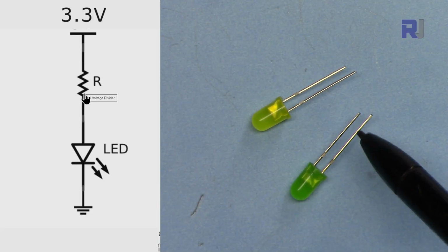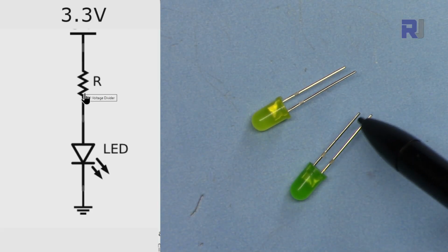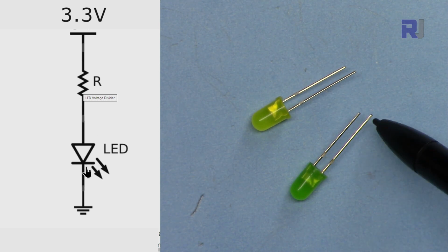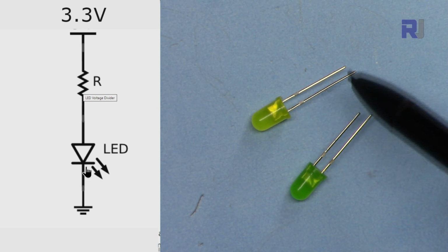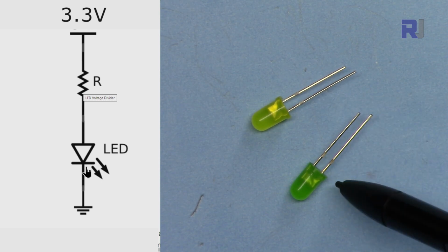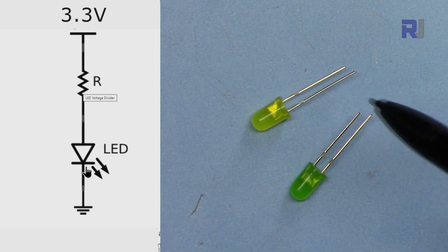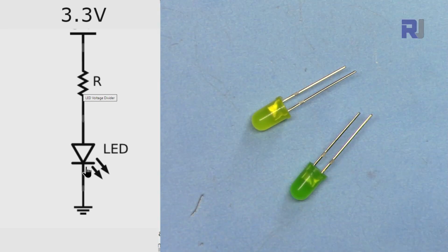We talk about the LEDs first. The LED has an anode and a cathode, and here this side is the anode, and the side that has a line is the cathode. Anode is always connected to positive and the cathode is always connected to negative, meaning the anode side should always have a higher voltage than the cathode. The longer pin is the anode, and the shorter on the other side is the cathode, meaning the longer pin is connected to positive.